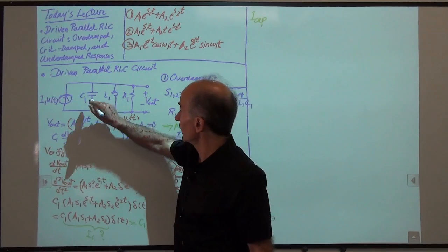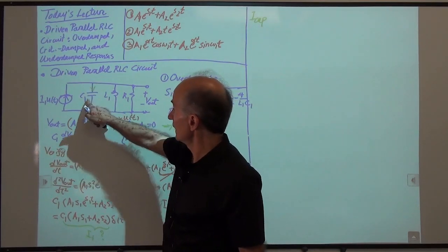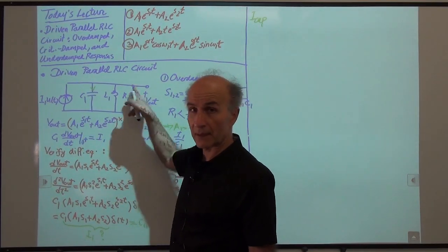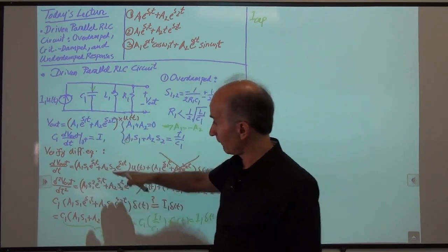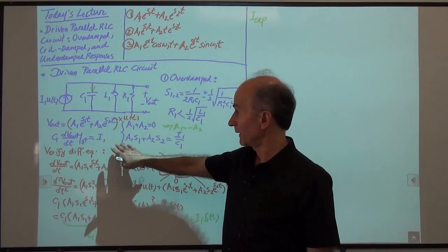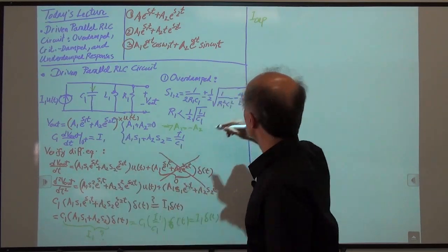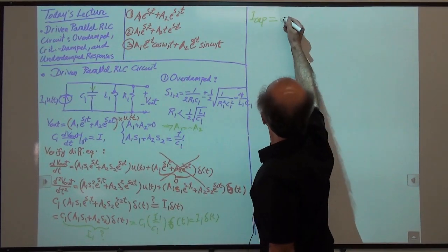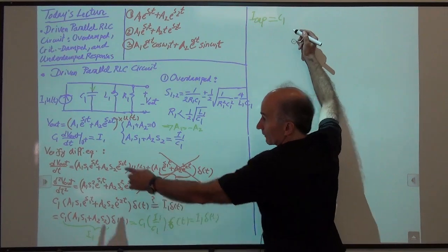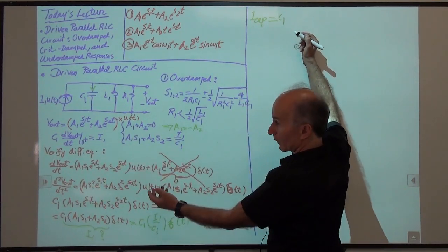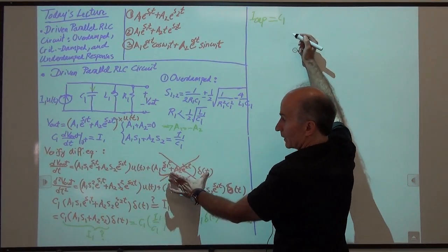All right, not a problem. We know that the capacitor current is just C1 dV out over dt because it's the same voltage. And we have V out, so we can just go ahead and take the derivative of V out, right? So we say it is equal to C1, then the derivative of this whole thing, which we tried before, right here. And this is 0.